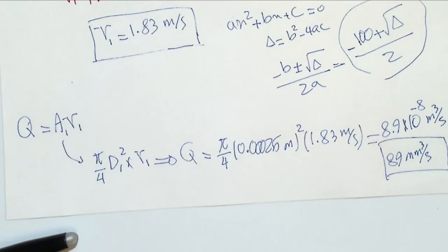So you saw how we solve this type of equation. Anytime you need to know which equation to use, laminar or turbulent, you always have to find the Reynolds number. Then when you find the Reynolds number, you can say whether it's laminar or turbulent. And then you can use the equation that we provided in chapter 8. I hope you enjoyed the class, and this question and recitation helps you to solve the questions you have in the homework.